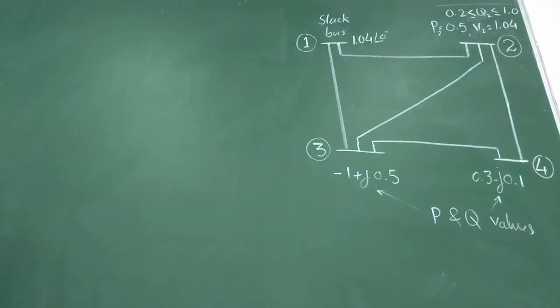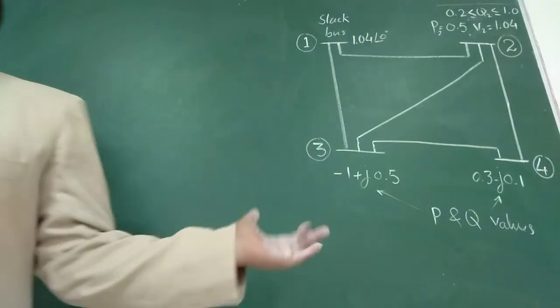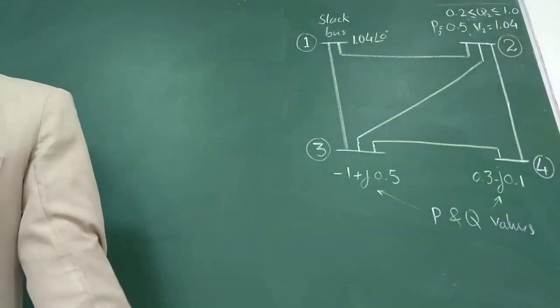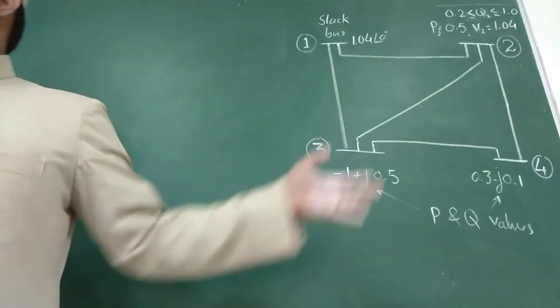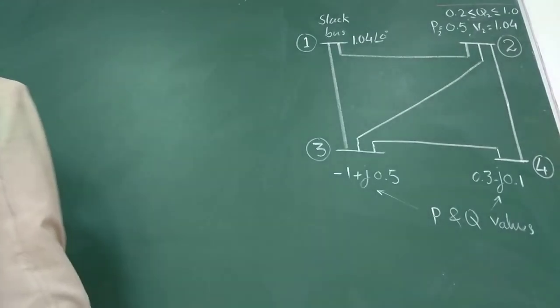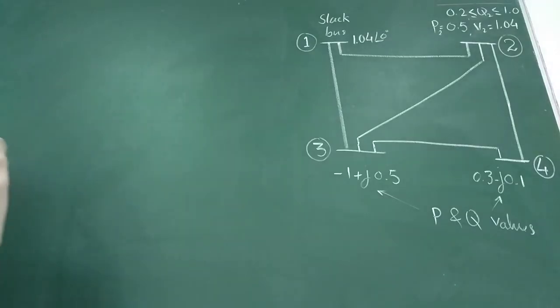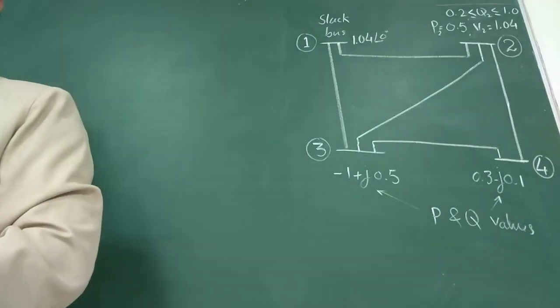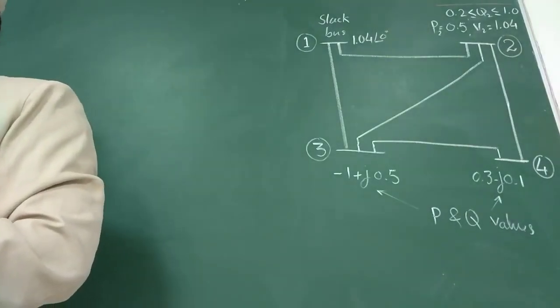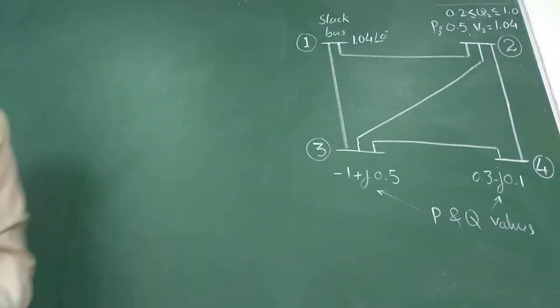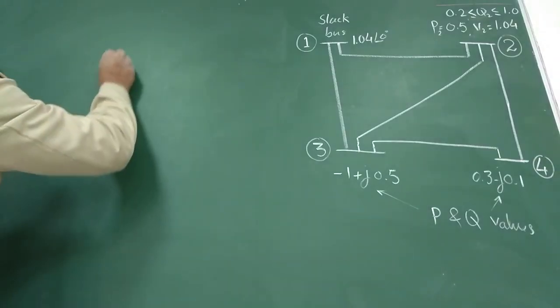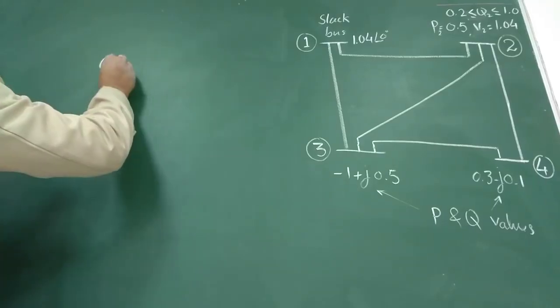So how to start? For the same system. So till now we have system data, we have Y bus, same Y bus. Whether buses are PQ or PV, Y bus will be same for the same system. So for bus number 2, first we need to evaluate which variable? Q. So right here, formula of Q. So Q2 is not it.